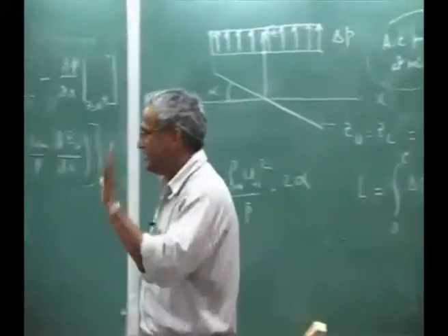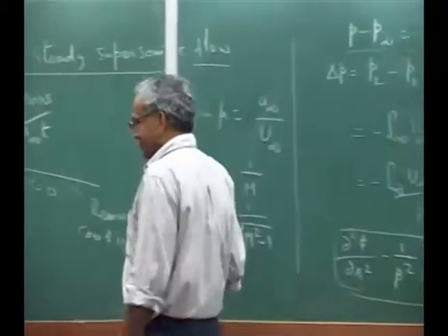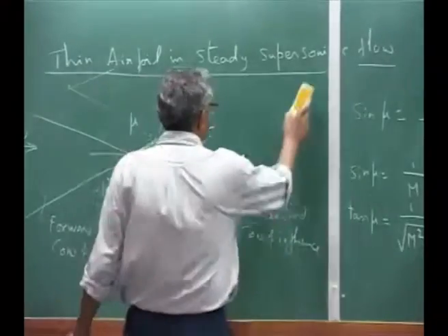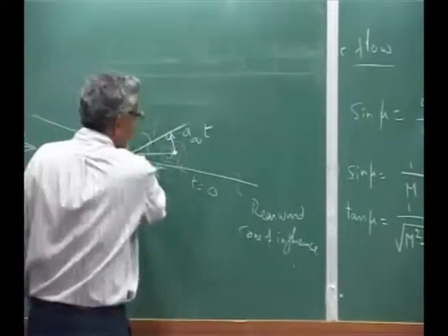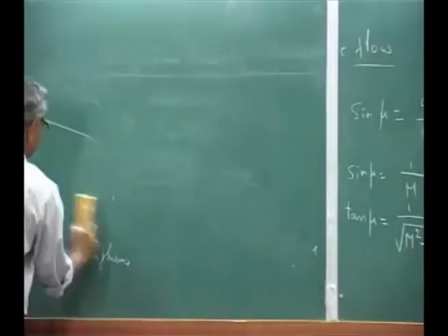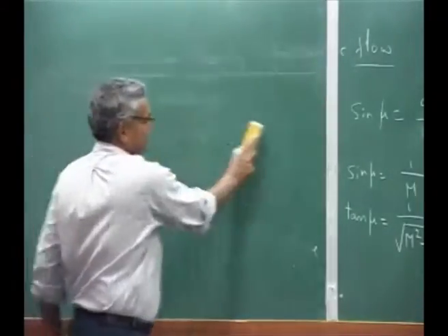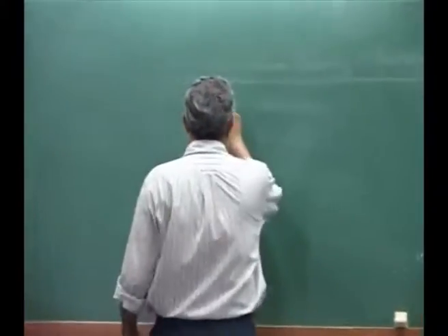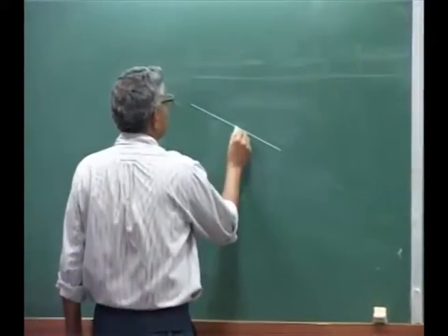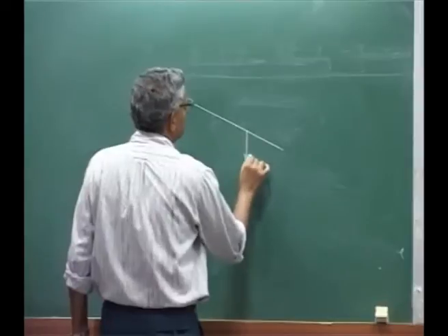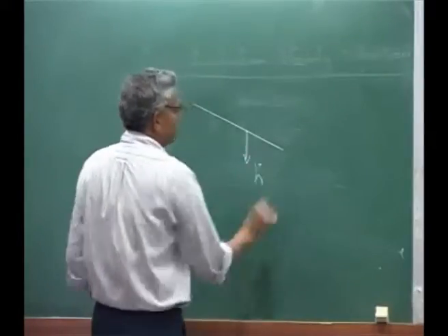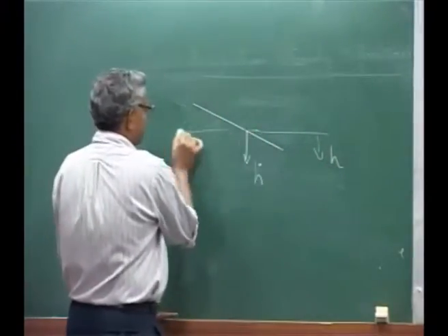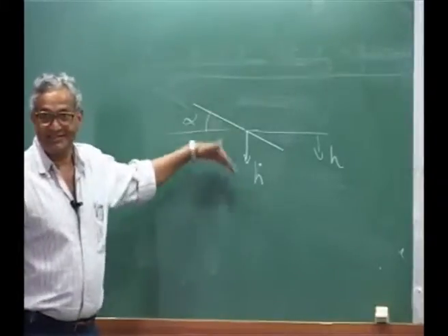Suppose it is an unsteady airfoil. The same approximation which we made earlier when we were doing the simplistic analysis of flutter, you can use it. That is, you say effective angle of attack. Suppose your aerofoil is also coming down with a velocity h dot, because you know that this is how we defined our h and alpha for the aerofoil.